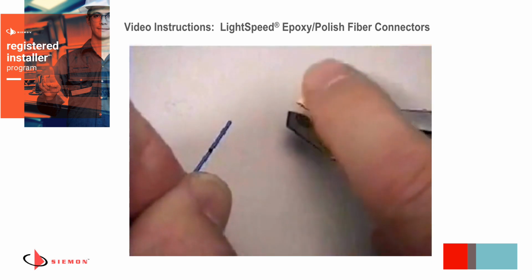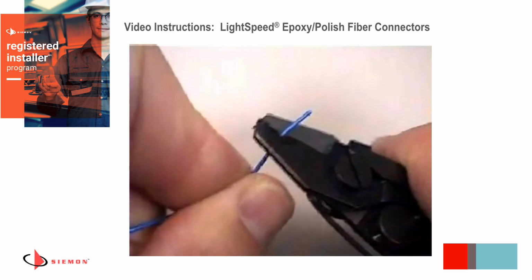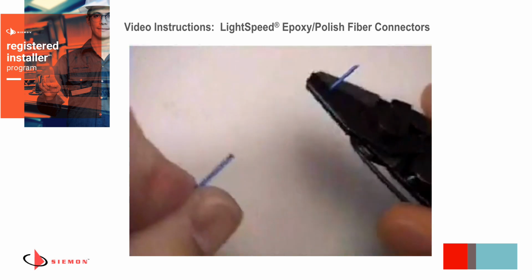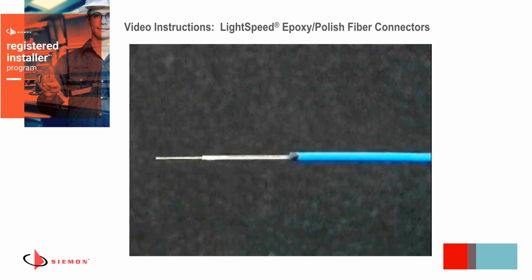Carefully inspect each fiber after stripping to be sure the protective coating was stripped off during this process. With some fiber types, under certain conditions, the clear protective coating may not strip off along with the buffer. Notice the partial protective coating remaining on this fiber after stripping. Sometimes mistaken to be the fiber cladding, this coating must be completely removed for the fibers to fit in the connector.